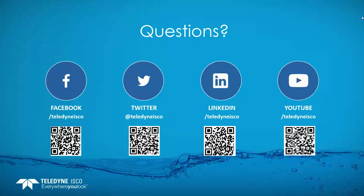The first question is addressed to Andrew. Can flumes be freestanding? Yeah, that's a great question, and the answer is yes and no. Some smaller partial flumes, anything under 6 inches, and some Palmer Bowlus flumes can be freestanding. But larger flumes are designed to be liners, and they need to be set in concrete and completely encapsulated in order to keep their rigidity and strength, and your tolerances and dimensions.